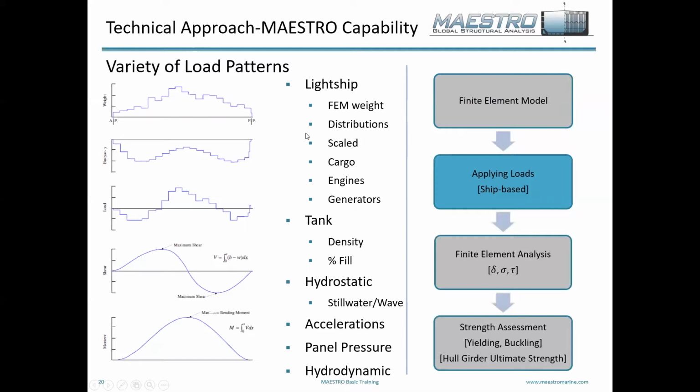You have the ability to scale weight for a given module or something. If you know it's heavier, say you have a piece of equipment or mast or some structure, you can simply scale the entire mass of that piece of the model. Rather than adding discrete weight to it, you can scale the existing structural weight to account for something.